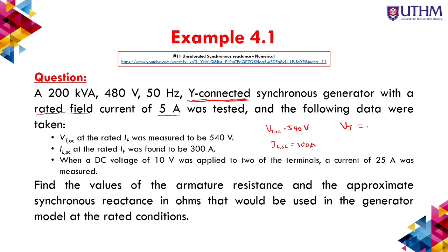Okay, so for Y connected, VT is equal to square root of 3 times V phase, where the IL will be the same as IA. So in this, we can already get a few parameters by knowing this.